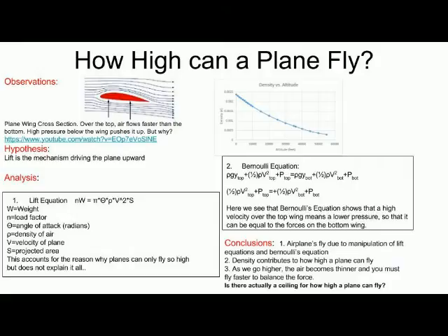Lift depends on the density of the air, the square of the velocity, the air's viscosity and compressibility, the surface area over which the air flows, the shape of the body, and the body's inclination to the flow. In general, the dependence on body shape, inclination, air viscosity, and compressibility is very complex.